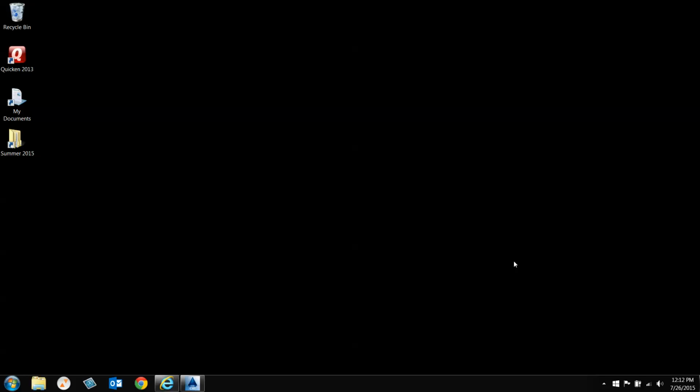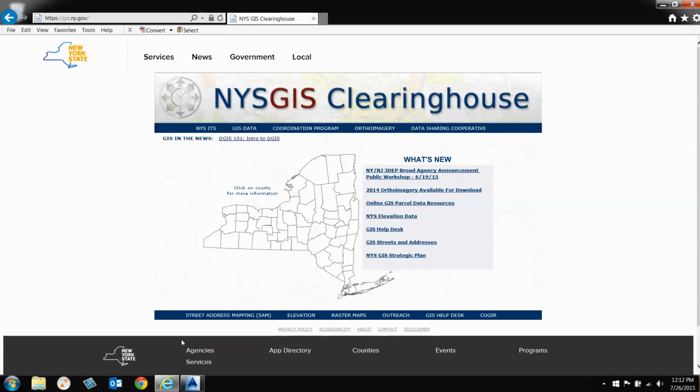Alright, thank you for coming to the Municipal Engineer website, and in this tutorial I will be showing you how to download and insert ortho imagery into Civil3D to scale and to coordinates. So when you're done with this, you'll have some nice image files that you'll be able to lay out some utilities in actual lengths and start to get some rough quantities.